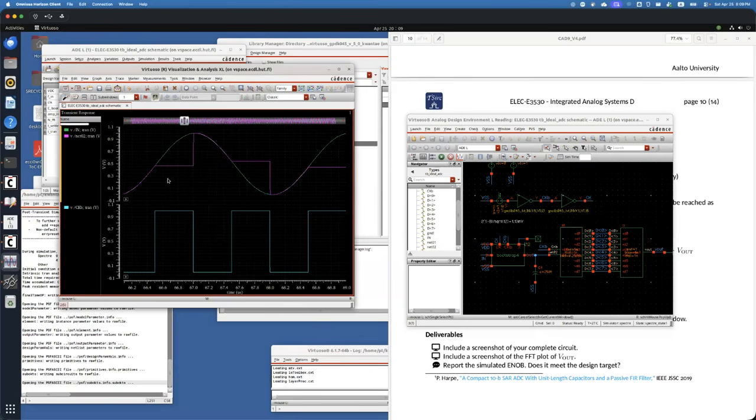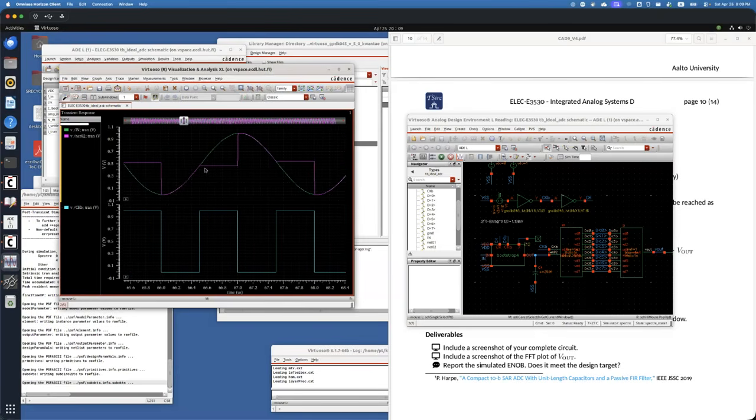For the clock bar, you can see that it has a track period and a hold period. And within the hold period, we want to do the quantization. So we want to set the clock bar here within the hold period. So when a hold is set, then we want to run quantization with 25% of the period as delay.